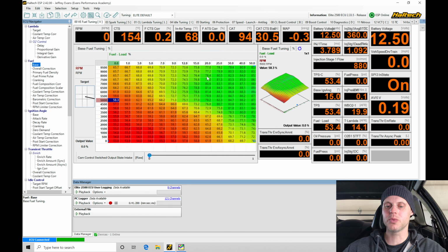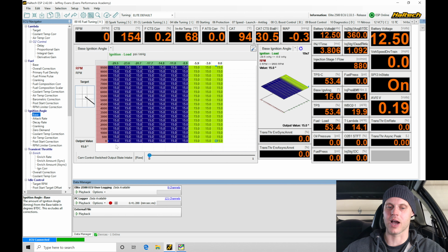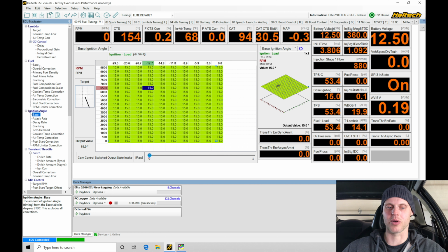0 as possible. Once we know this table is well tuned, then we can jump back into our spark timing table and we can start to experiment with our values in here and optimize them so we're getting close to maximum or at maximum brake torque, so we can achieve the most amount of efficiency and throttle response and torque output from our engine, again, in the cruising situation. So we're looking essentially in these columns right here. So let's go fire up the engine right now and let's start our process.